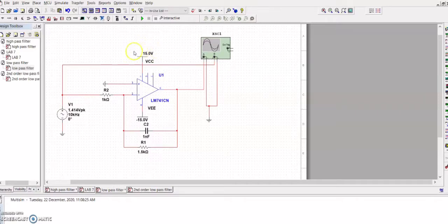Then we use 15 volt of V input as referred in the Texas Instrument datasheet. As our voltage doesn't have a VRMS value, we change the 1 VRMS to 1.414 V peak. So now we're going to run it using 10 kHz of frequency. Let's see what happens.